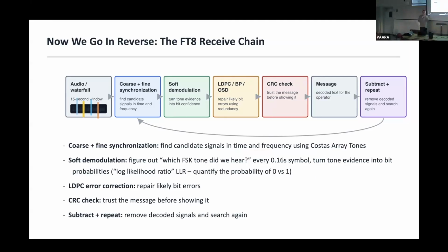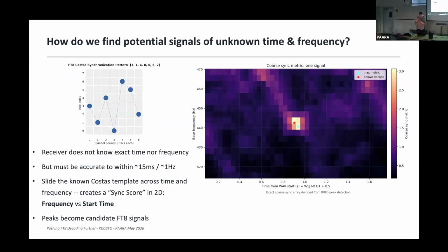And so, you saw that image earlier. It's like everybody's all transmitting on top of each other, but you can still pull out codes from signals that are at least partially under much stronger interferers, because it does this subtraction process, and then it runs that whole thing again, up to like 9 separate times. So it's really quite a computationally intense process as it exists today, and that's part of the challenge, like maybe making it more efficient.